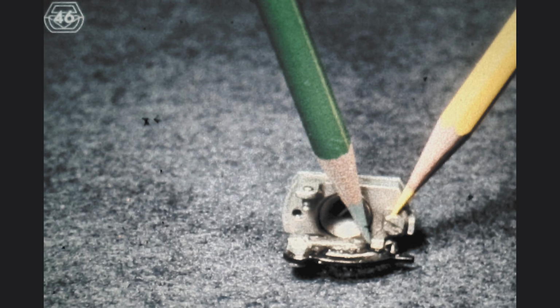Notice also the amount of lubrication found in these mechanisms. When you clean a machine, be sure to properly relubricate these areas. There is a tendency for the office machine repairman not to grease these spots because they are barely visible, easy to forget, and hard to reach. Failure to lubricate these points will invariably shorten the life of the machine.